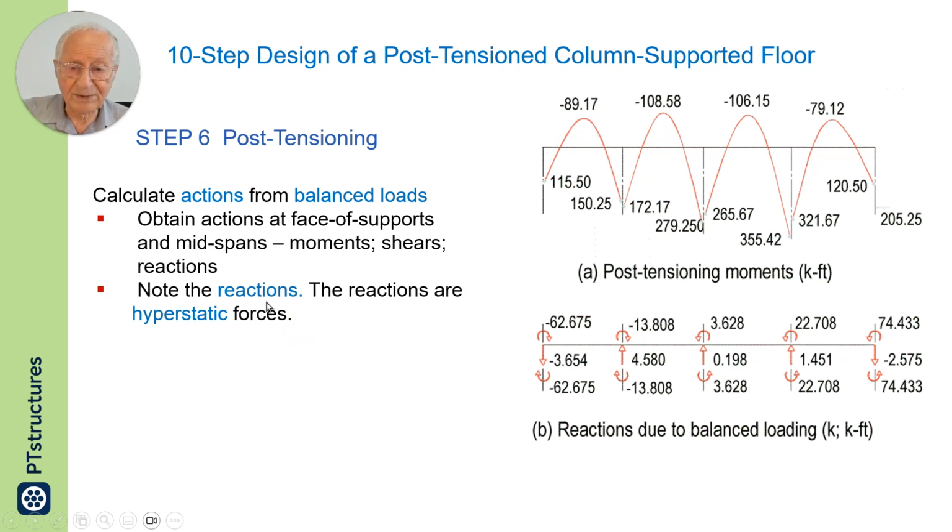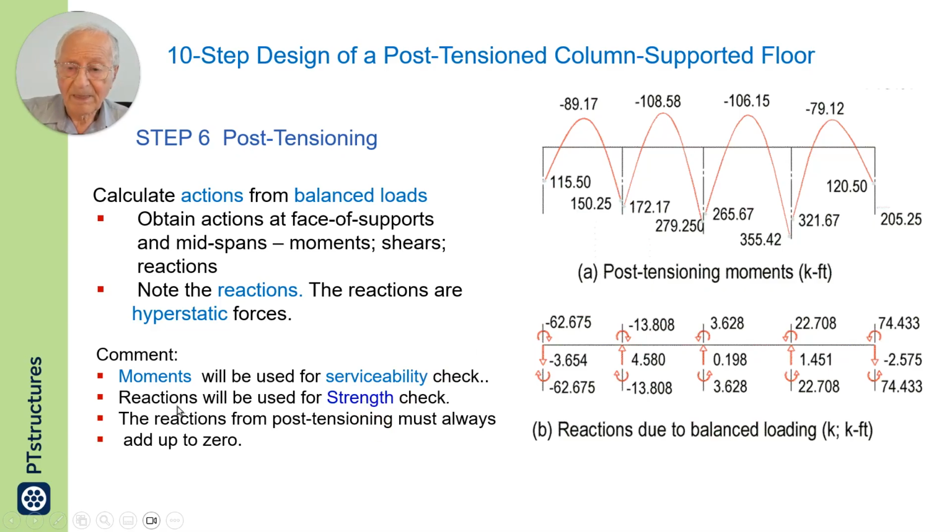Note the reactions. The reactions are hyperstatic forces. This is the definition of hyperstatic forces. Moments will be used for service check here. Reactions will be used for strength check. The reactions from post-tensioning must always add up to zero. These must always be zero because the post-tensioning itself, the balance loads which we applied to the frame were in equilibrium, therefore these must add up to zero also.